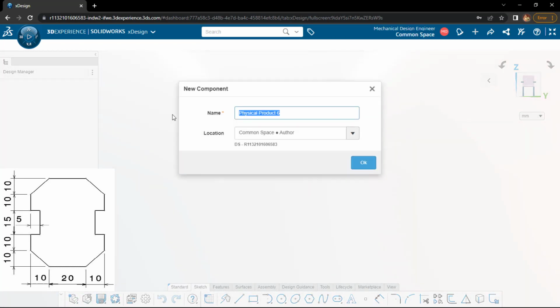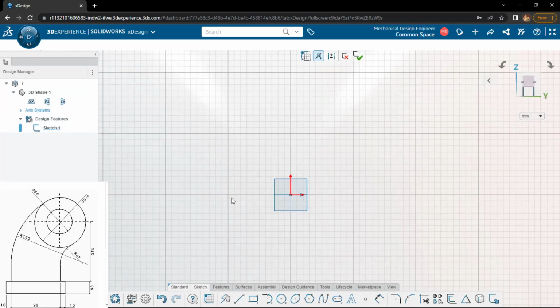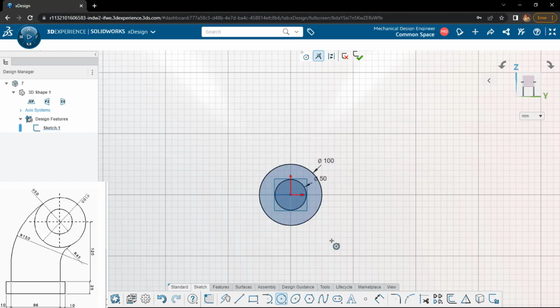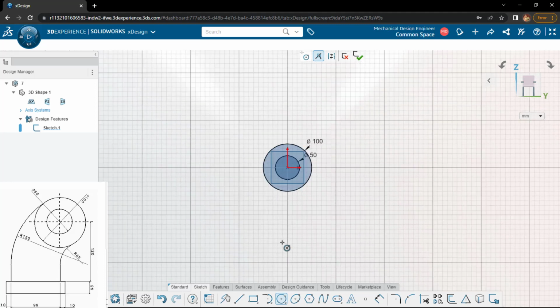Now I'll go ahead with one more. It's a bit of a complex one. So let's create the sketch, right? We have to start with the origin and two circles. So I'll do the same thing. See, for the circle, dimensions are given here. You can enter the same thing, 150. Done. So now I'll activate the shortcut key S, and you can select the rectangle. You can even use the sketcher ribbon tab, and from here I'll do it like this.